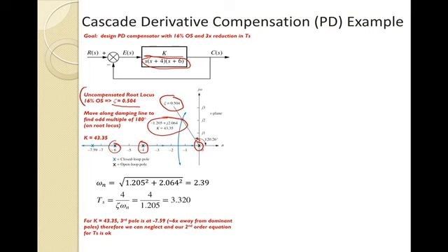So that's that location. And this on the j omega axis right here, we know this is our j-axis. We can call that omega d, the damped frequency, which is also going to be equal to the natural frequency times the square root of 1 minus zeta squared. So given this information, we know where our pole is. We can go back, we see it relative to here, and what we can do is find the natural frequency.